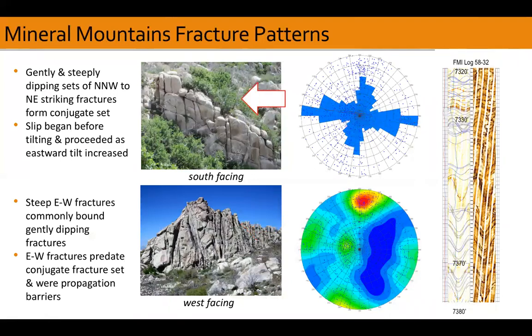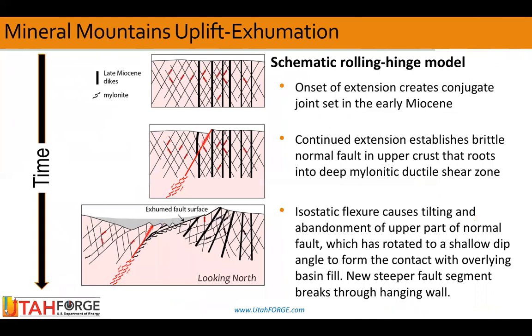The other 2 fracture sets represent a conjugate pair. One has a very steep dip that is near vertical, and the other has a dip that is inclined at a shallow angle to the west. The azimuth of this conjugate pair is north-northeast, south-southwest.